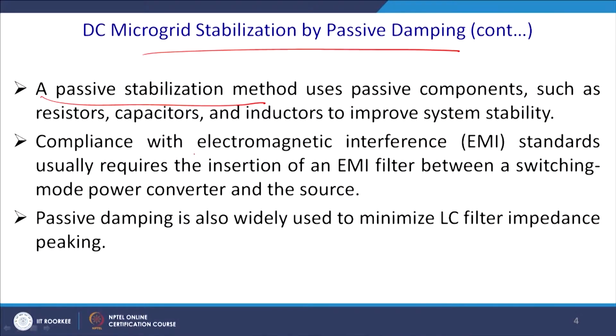Compliance with the electromagnetic interference standard is a challenge once you have this kind of issue. Generally, once you have sustained oscillation, you have a huge problem of EMI and EMC, and what happens is that once you suppress one entity, you will find that you have aggravated another entity.